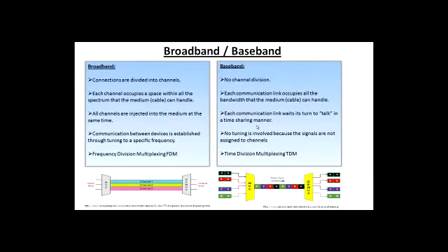The transmitter or the receiver is tuned to the transmitter, and that's it. It stays that way. And everything else, the channel division, is done by time sharing. Okay? Now, no tuning is involved because the signals are not assigned to channels. So that's the time division multiplexing.